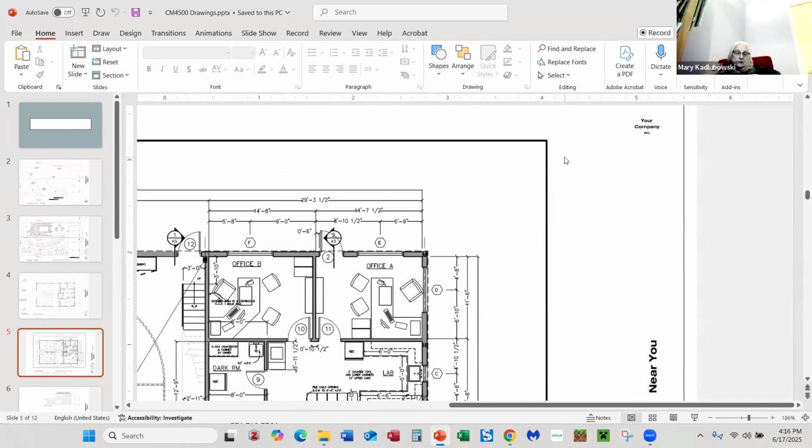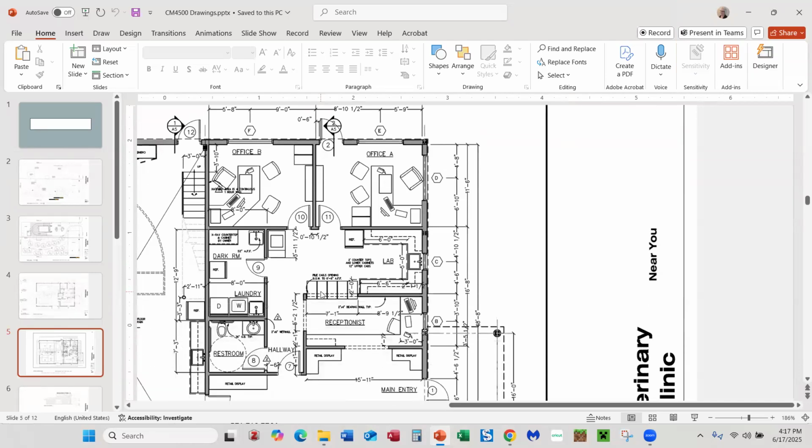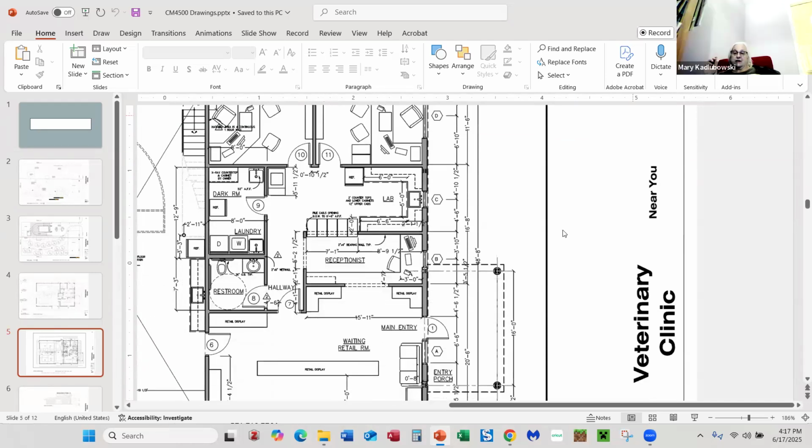You're going to put the symbol for your sconces, and the symbol for your overhead, probably an LED light because there's a lot less demand for LED, right? Anytime you add something here, you want to make sure it gets on that schedule. You may want to separate your lighting plan from your electrical plan, just because it gets really crowded.